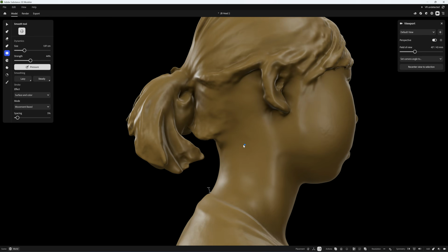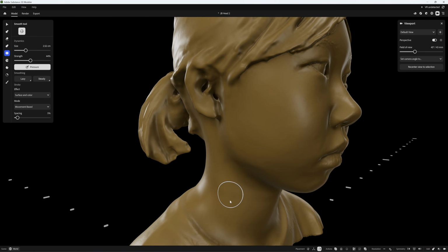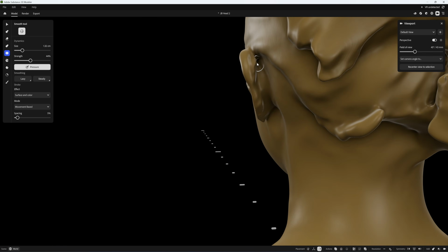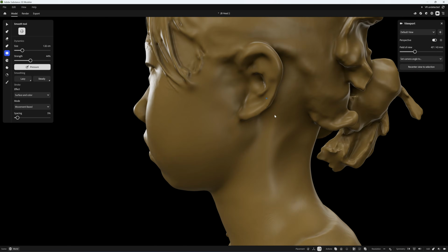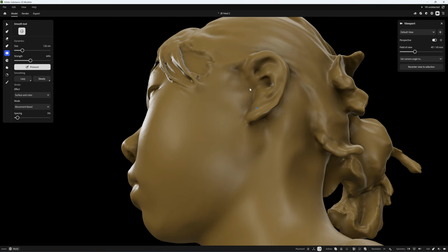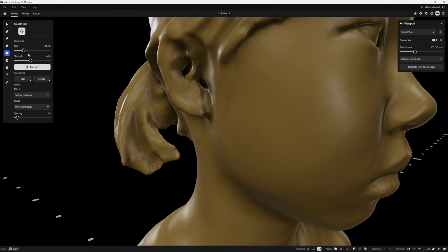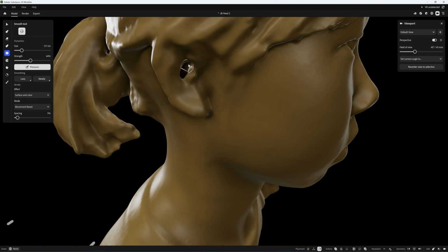Last year when I repaired the model, I still used Blender, but this one is far more advanced and easy to use. Left ear is more complete, so I'm going to smooth this one out first. This one is more complete. But on this side of the ear, let me fill this hole. This hole shouldn't be there. I'm going to use the build up tool. Increase the size, add the strength, and I'm going to fill the hole here. Okay, and this hole I'll smooth it out.